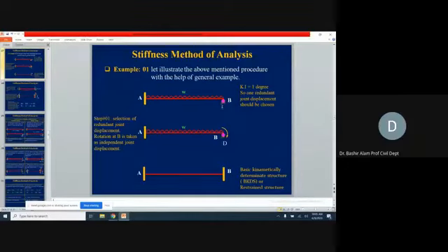How these 2 degrees at joint B, if you see it, can translate in the horizontal direction, and it can rotate also at this joint B. So these are the 2 degrees of indeterminacy. But now, if we ignore the axial effect, this horizontal translation is gone, and we are left with only rotation at B. So we take this kinematically indeterminate 1 degree.